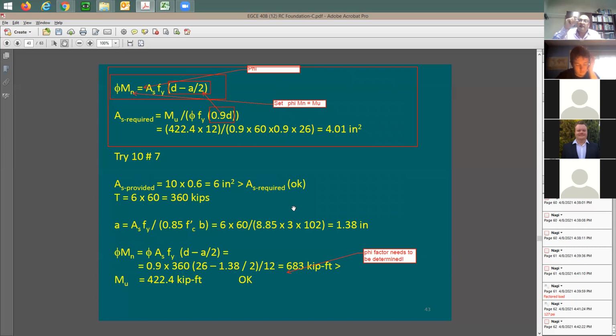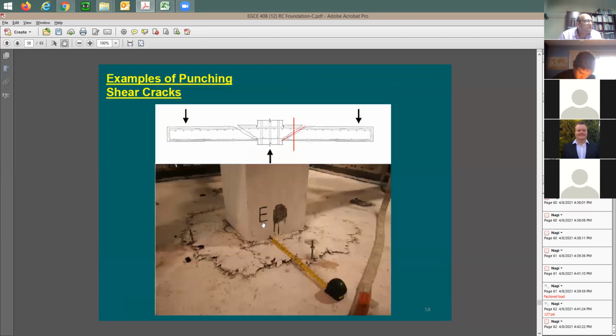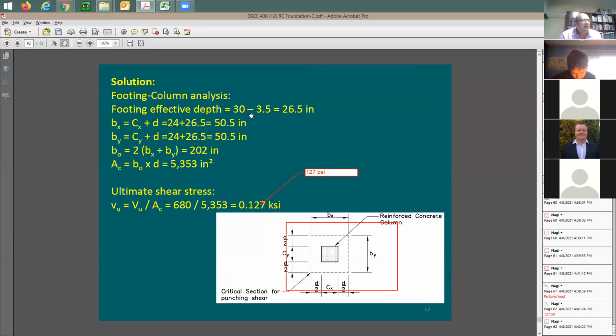So I said, the clear cover is gonna be 3 inches, and to the center of the rebar is gonna be how much? Half an inch. So I said, total is gonna be 3.5 inch. And if I may go back here to my slide, it is gonna be half an inch. So 3.5 inch is what? Let me put it down here. It is gonna be 3 inch cover plus 0.5 of dB, the bar diameter, which is number 8 or number 7.